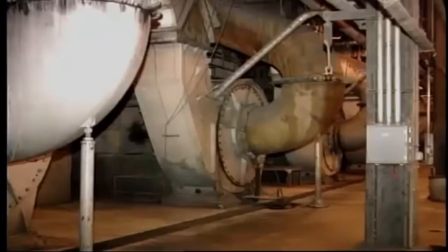But as with all things, there is a downside. In this arrangement, the exhauster fan is conveying both primary air and fine coal dust on its way to supply the burners. The result is a great deal of erosion and wear on the fan internals, requiring regular downtime for maintenance. Now, how do we control the heat input, that is, the fuel input to the boiler, from the burners?